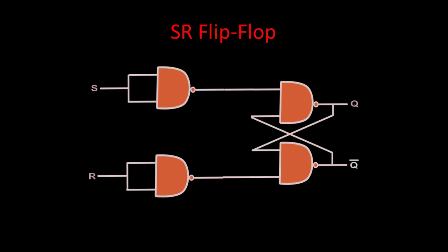Because this flip-flop is symmetric, whatever we have in the upper part, we have in the lower one. So with 0 1 we got 0 1, and with 1 0 we will have output 1 0, going by the same argument as in the previous state. So with 1 0 we have 1 0. Because Q becomes 1, this is called the set state.